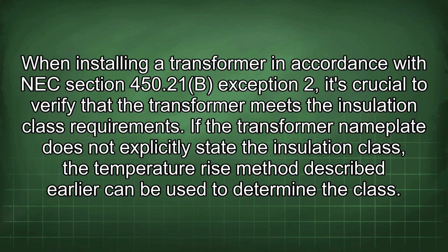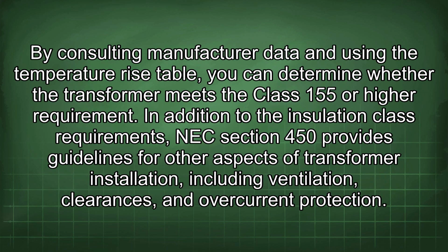If the transformer nameplate does not explicitly state the insulation class, the temperature rise method described earlier can be used to determine the class. By consulting manufacturer data and using the temperature rise table, you can determine whether the transformer meets the Class 155 or higher requirement.